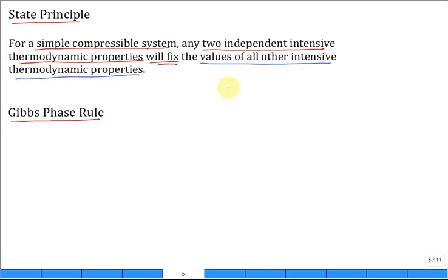And we had a whole list of properties, didn't we? We started with maybe pressure, temperature, specific volume, internal energy U, then we had H and S, and then G, you even have the Gibbs function, the Helmholtz function, you could even throw in specific heats, you just have a whole pile of them. But for the types of systems that we've been studying, typically temperature and pressure, those are the two we like to have as independent.